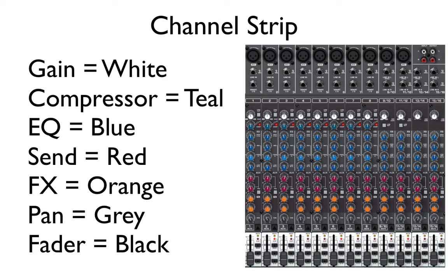Each signal that is an input into the mixer has its own channel, and depending on the specific mixer, each channel is either stereo or mono. On most mixers, each channel will have an XLR input, and many will have an RCA or quarter-inch line input.